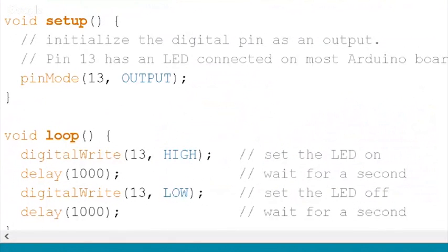It is very simple. In the Blink program, what I've written is void setup. Why I've given void: this system will not give me any output, it's not going to send any arguments out. So I've given void setup. This runs once, where I am setting the ports. So pinMode. You can see here, pin P is small, but in Arduino, every second word has no space but starts in capital. PinMode, the 13th pin, I am putting as my output pin.